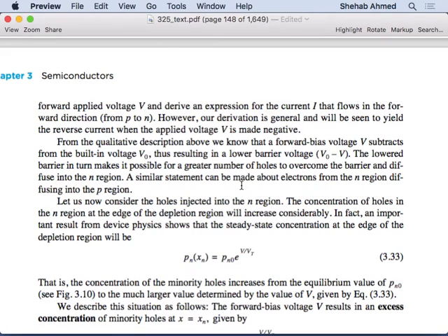This difference in concentration happens to have an exponential characteristic. As soon as you hit the N-type material, what is the theoretical concentration of majority hole carriers? Almost zero at the N side, right? But at the beginning of the P side, a lot of holes if I'm injecting from one side. So it's like an exponential function here.